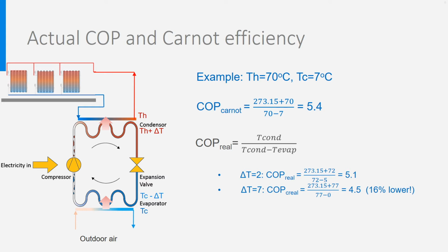By the way, at cold temperatures, a defrost mode is needed, otherwise the humidity contained in the outdoor air would condense and freeze on the evaporator, which would decrease its performance a lot.